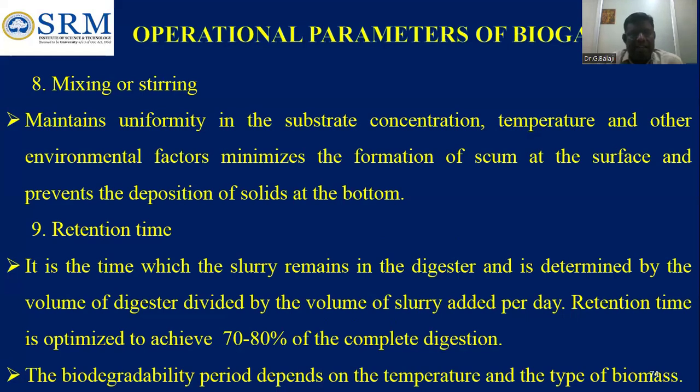The retention time. As I said, each source will have a different retention time, different digestion time. Whatever the source we use, accordingly we have to give the retention time and design the digester.